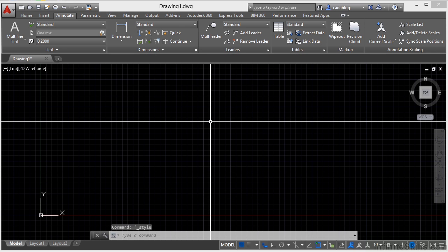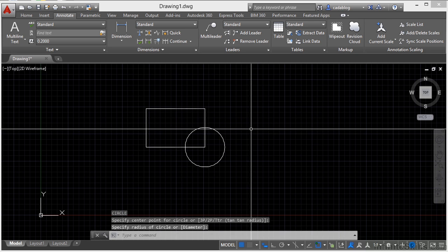Now there is another type of tab that will show up in the ribbon from time to time, and they are called contextual tabs. These tabs are not accessible at the moment, but they will show up when a certain command is activated. These tabs will contain tools that you will not need or be able to use during your normal working conditions. But the contextual tabs have tools in them that you will need in special cases. One example is the Hatch tool.